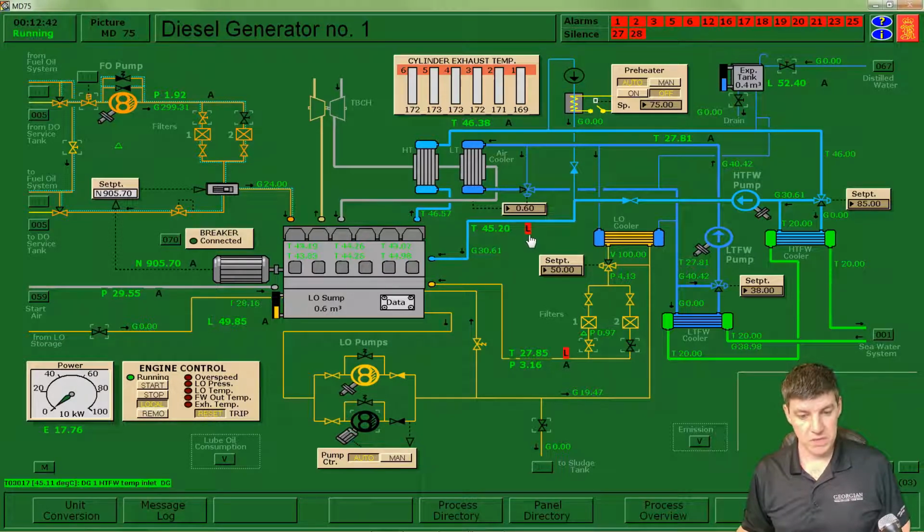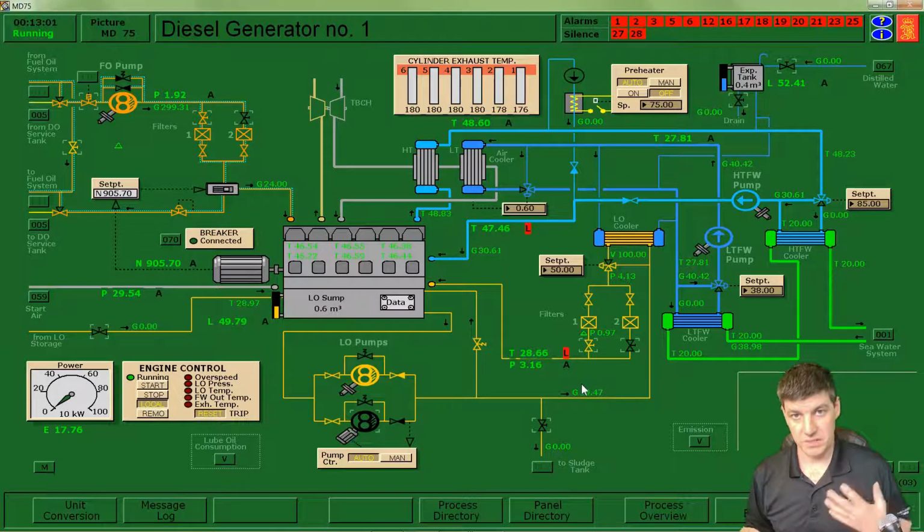What we want to make sure is that we don't have high temperatures that exist, which means maybe we lack cooling water or we've run out of cooling water. Those could be all symptoms that exist. So really at this point, we would just have these two low-level alarms, and we would want to make sure that all of our systems are stable. Okay, and that would be a measure of success for us in starting up this generator.